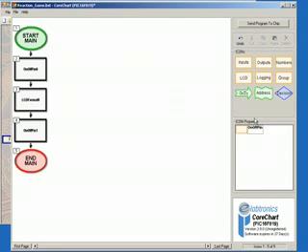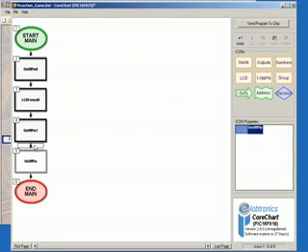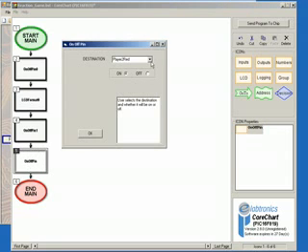We want another output, so again we'll select outputs then on-off pin, and then place it by clicking the black arrow below icon 4. Double click on the icon to bring up its options, and select D7 yellow LED as the destination, and select on, and then click OK.